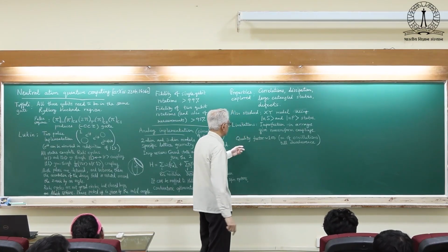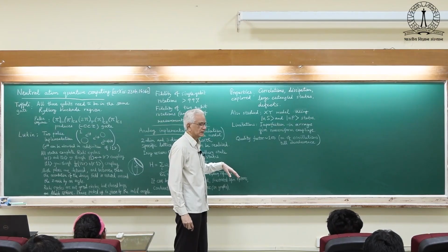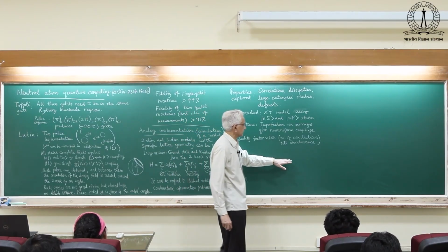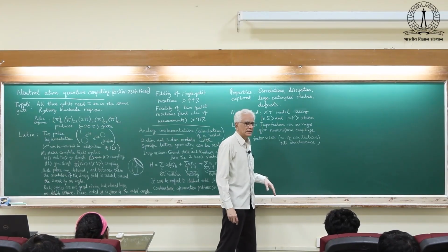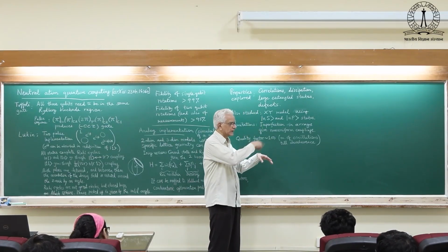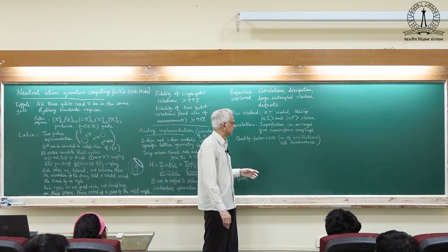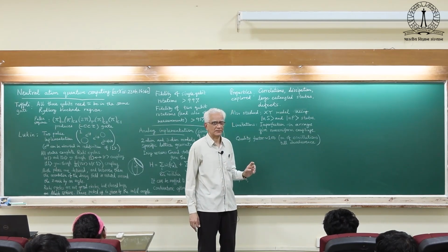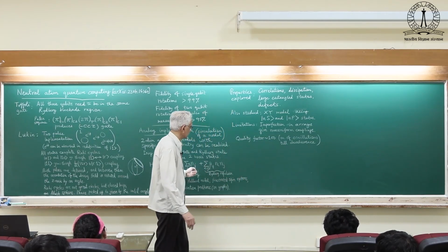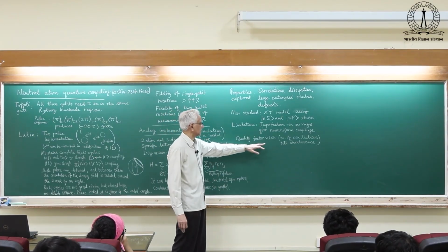This is a term which is taken from classical wave dynamics. The waves are not perfect, they decay in time, and the question is how many oscillations it will be able to perform before the whole system decays, and that object is called the quality factor. So in the analog mode, the quality factor which is achieved for these models is about 100.